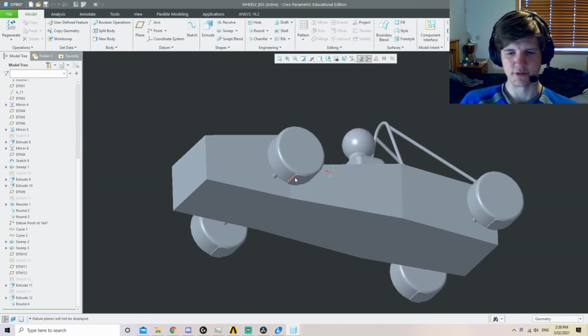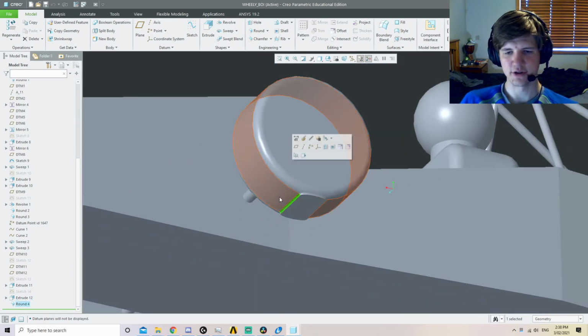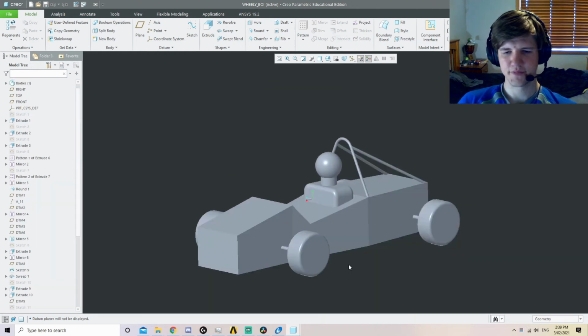Note for when creating the wheels, it is recommended to extrude something into the wheel and then put a round on that to ensure that the wheel has a contact patch on the ground and there are no points where the mesh can go to infinity. It is at this point where wings, nose cone and under tray would be attached. However, at this stage, those parts have not been created and thus will not be demonstrated in this tutorial.